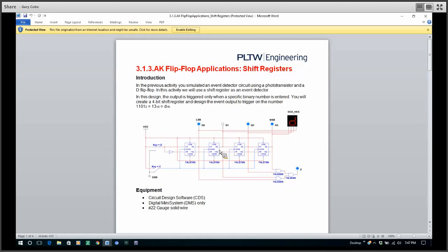These two are in one IC chip on the Design tab. They've got the little identifications up here: preset, J, K, clock. But they have numbers in front of them, 1 and 2. The 1 is the first JK flip-flop in the IC chip, the 74LS76, and this one's the second one in it.